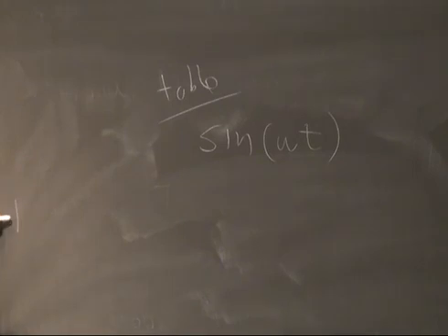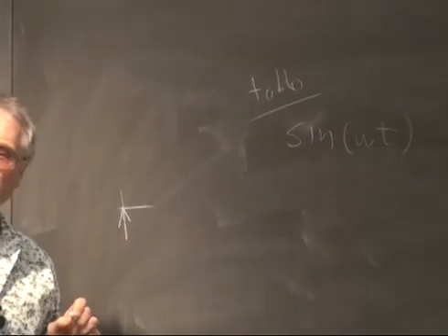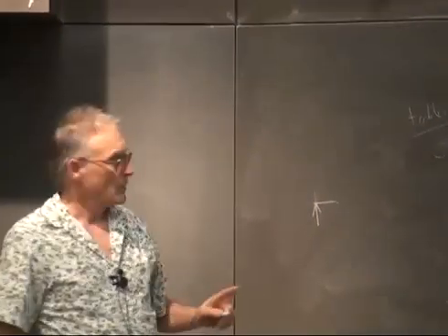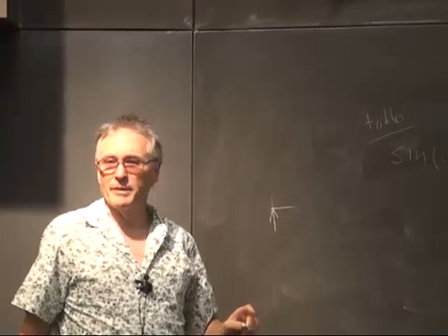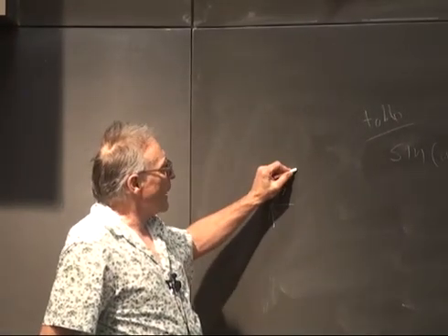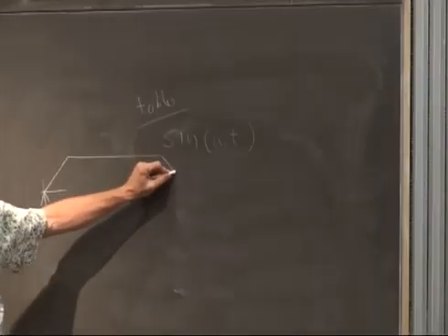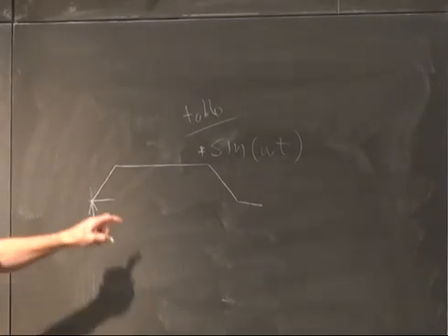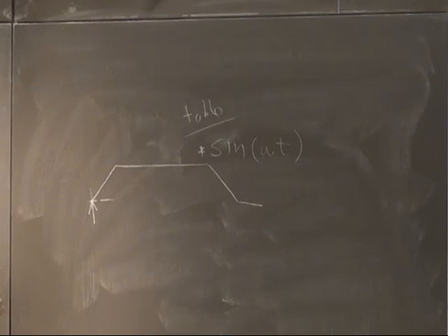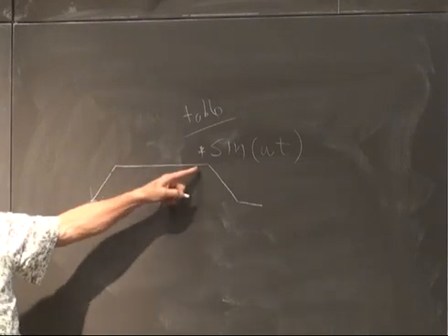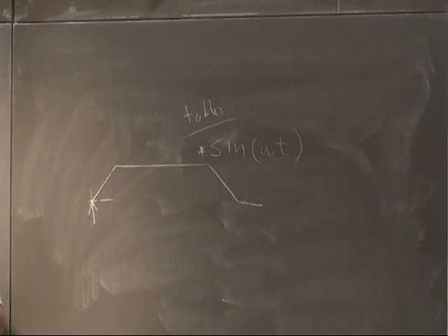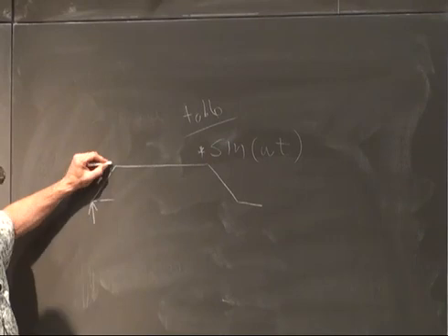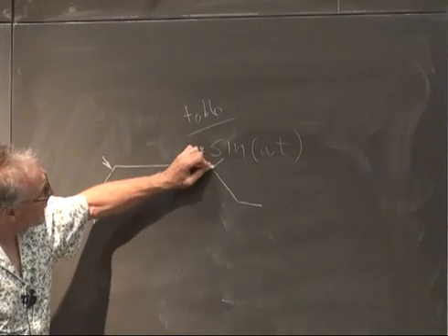Then you're going to have to figure out some way in your code to mark a time zero. And from that time zero, which will be the beginning of the burst, you're going to have to generate another waveform, which you're then going to multiply times the sine function. This waveform can be as simple as a linear ramp up, a hold, a linear ramp down, where the 65 milliseconds, that's the minimum time required for the DTMF standard, is measured from 90% to 90%.